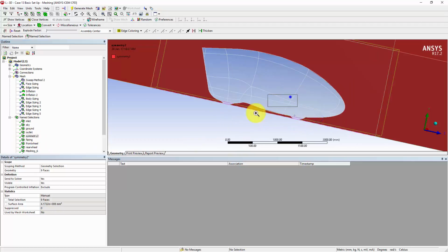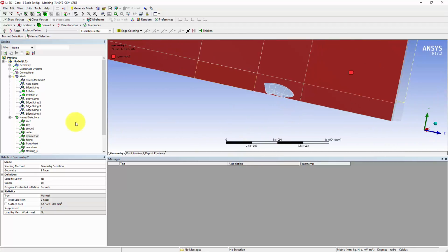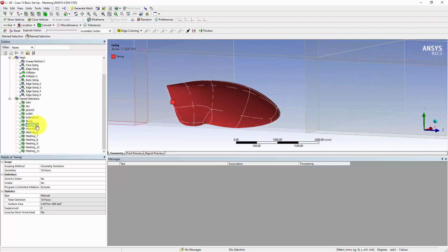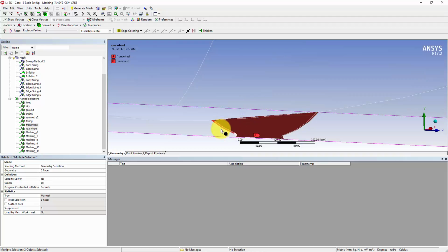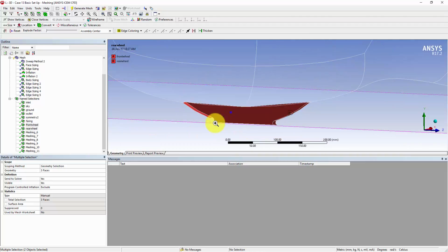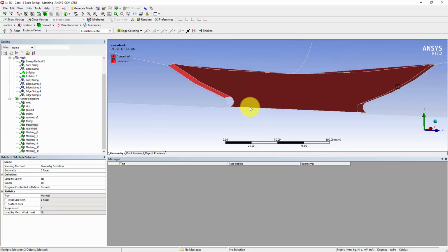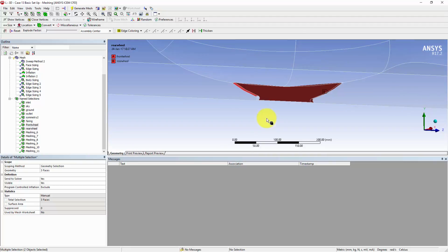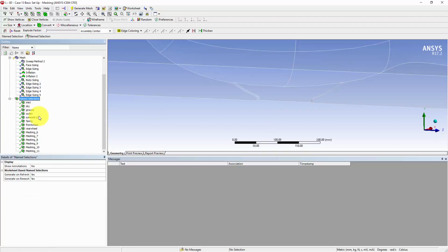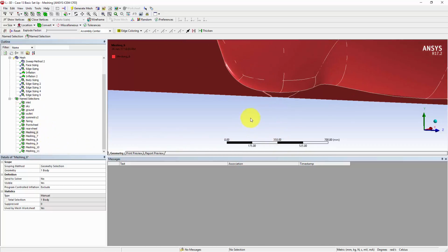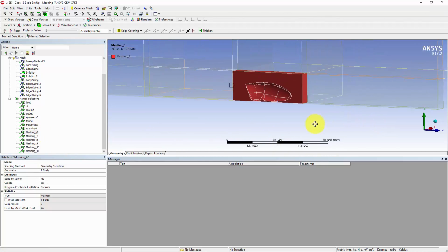symmetry 2 with that surface there as well, keep that in mind, the fairing, and also make 2 new selections for the front and rear wheel. Keep in mind, if you do select the fillet, that may also be a ground. Fluent will throw up some issues saying that you've created a named selection for one surface twice. And then go through and delete the meshing procedure that was previously created, and we'll remake them.